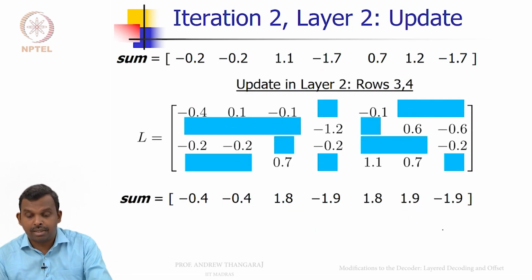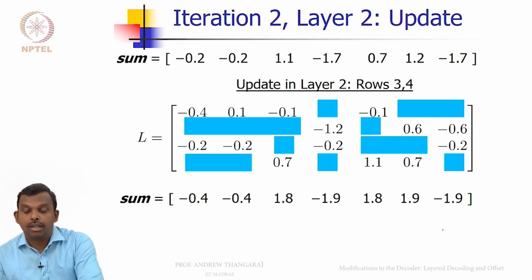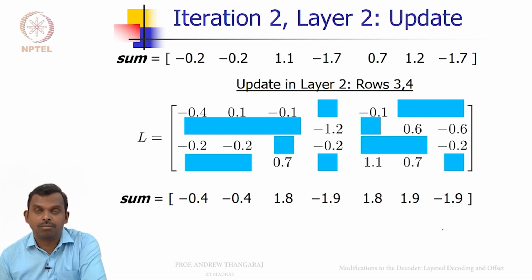And then once you finish the min sum, it's just the update. And you have the overall belief. So this is the step that's repeated again and again. When you want to do more iterations, you repeat the same thing: subtract, min sum, update, subtract, min sum, update.